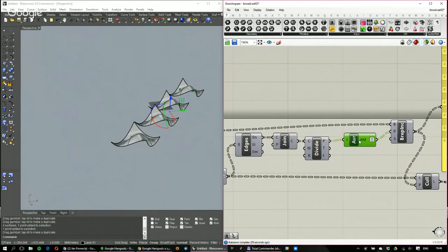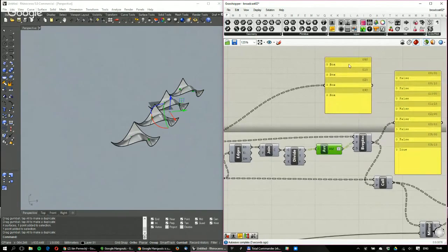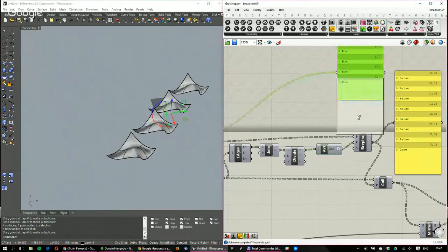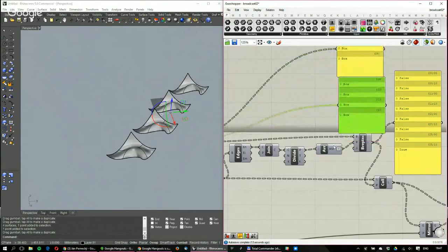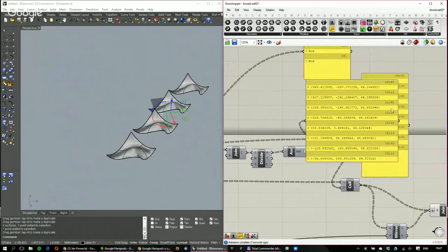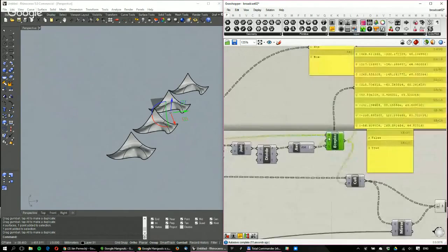Yes. So now I will show you what the problem is. The bounding boxes are distributed into the branches in this fashion. For each one of these objects, there is one branch, but the points that we are actually evaluating have a different depth of data tree. So there's the first and the second, first and second, first and second, and so on. And this is the problem, because if we are asking whether something is in the B-rep, these two data structures don't match.